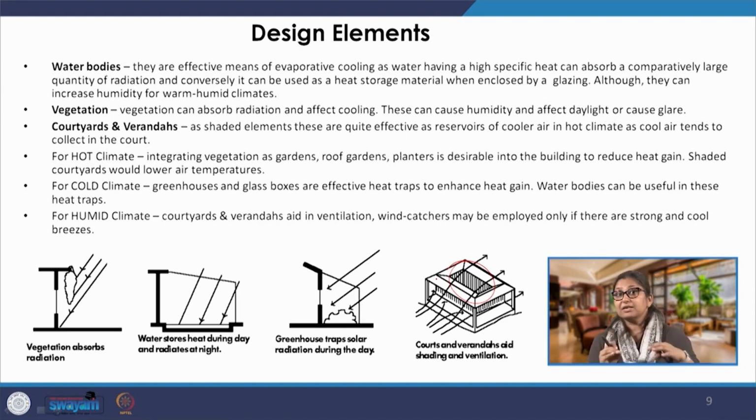That night ventilation will take away the heat; the walls and surfaces of the building will be cooled through the cool air passing through, and we have to allow cross ventilation, and courtyards allow that. So, what type of design element is required? In hot climates, we may use courtyards, and that is why across the length and width of the country, we have courtyards in traditional buildings.